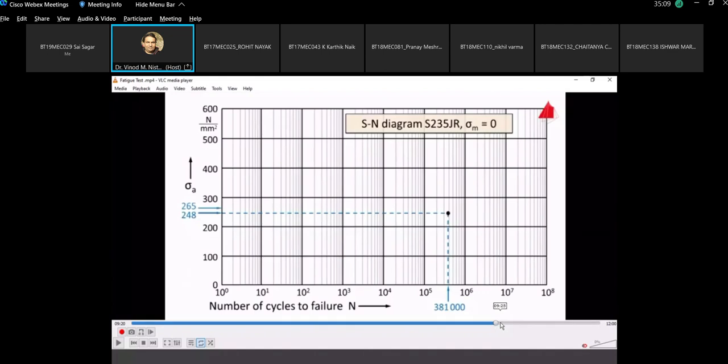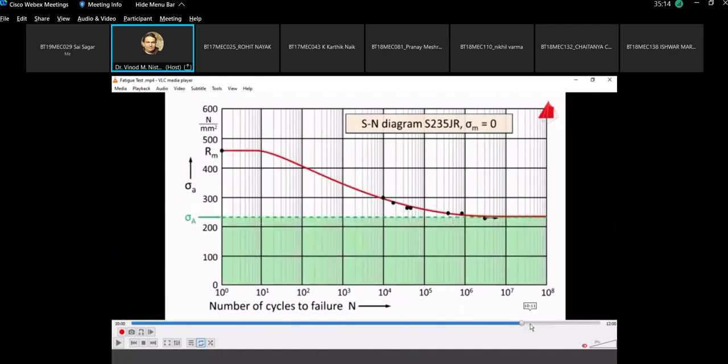And we will find an endurance limit, in order to see on an average what amount of stress we can apply on the material so that it will not fail for an infinite number of cycles. But no material can sustain infinite number of cycles. It will fail after some period of time. But the maximum number of loading cycles it can bear is the endurance limit of the material. So this is the purpose of performing this fatigue testing for cyclic loading.